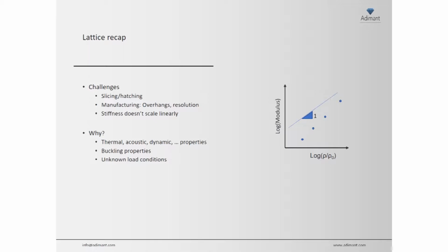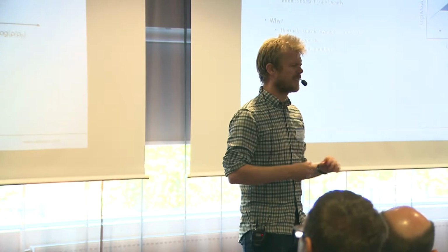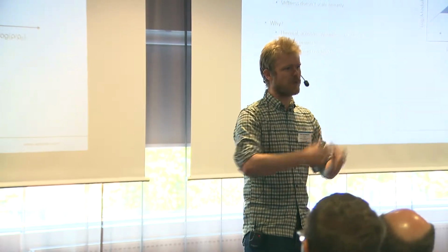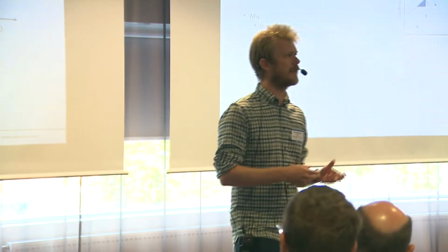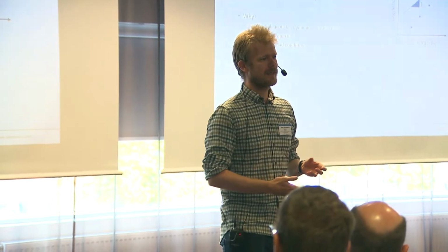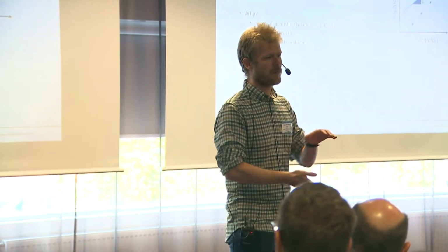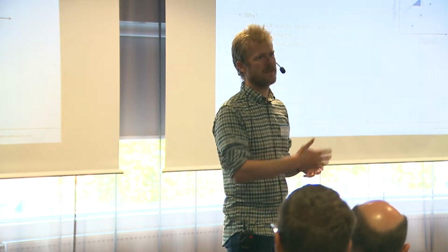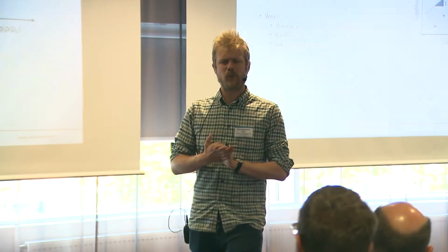You hear it a lot in popular newspapers, etc. It is simply wrong, because when you start to remove material from a part, your part is not going to be stronger. I'm sorry to say it. And actually it scales a little bit worse than just linear scaling. So your part is going to be not even stronger per volume or per mass, but it's going to be a little bit weaker. So why would you want to build lattice structures at all?